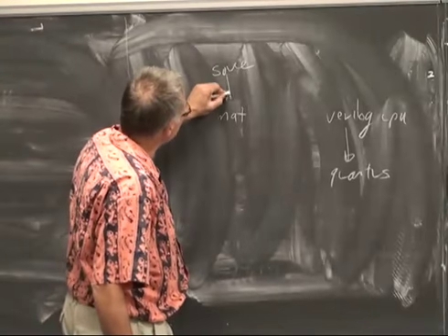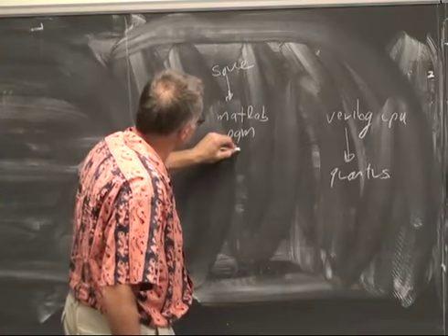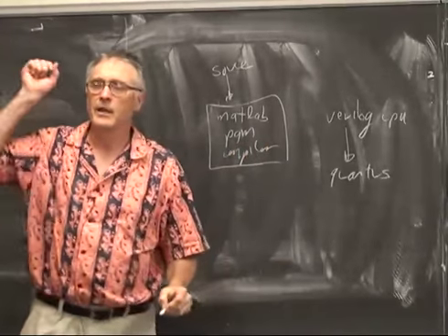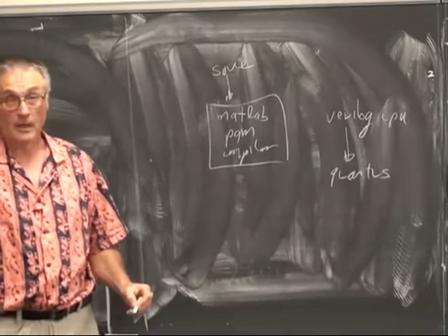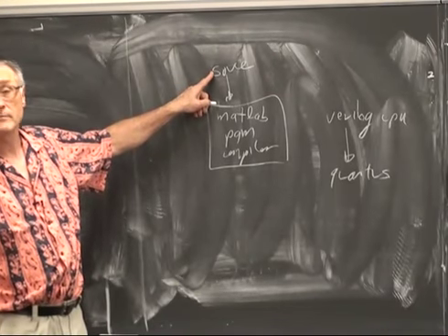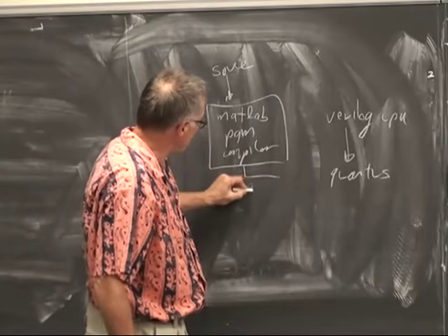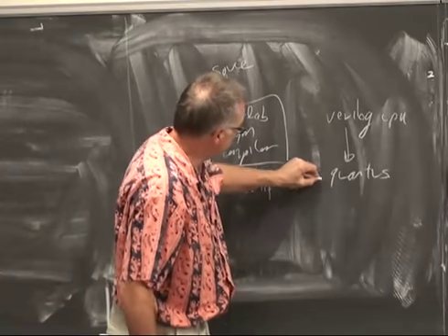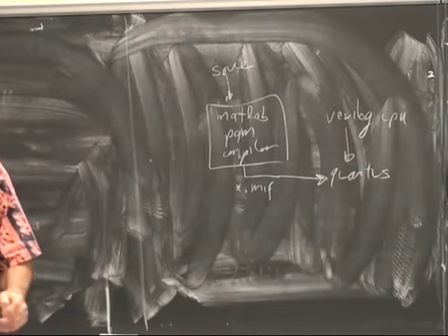So source code feeds into a MATLAB program, which is the compiler. This MATLAB program has exactly one parameter. You run it, and it opens a dialog box that asks for the name of a file. The MATLAB compiler then outputs a star.mif file, which you have to identify to Quartus by means of the synthesis directive that we talked about on Friday.